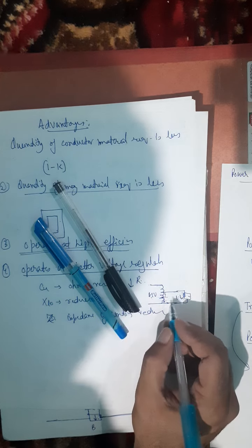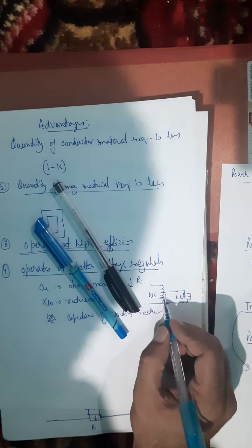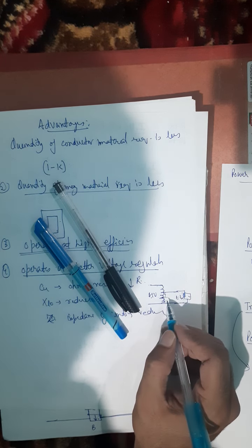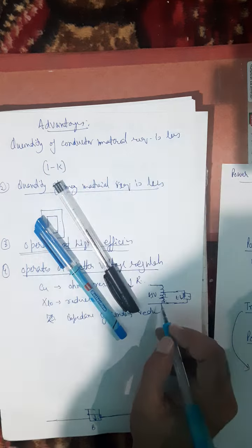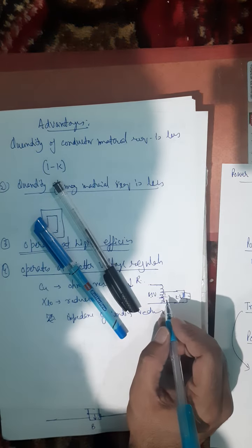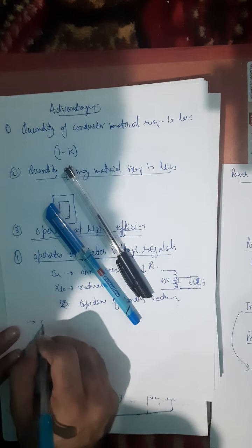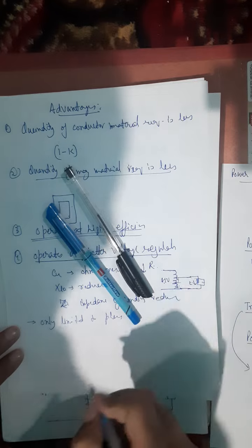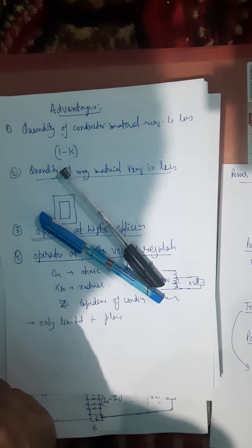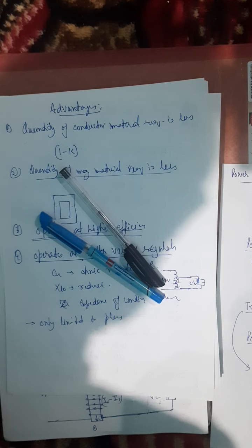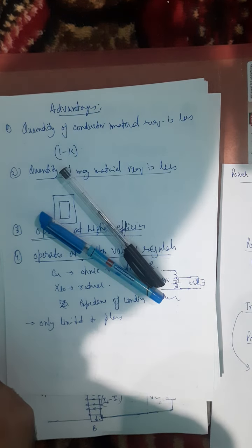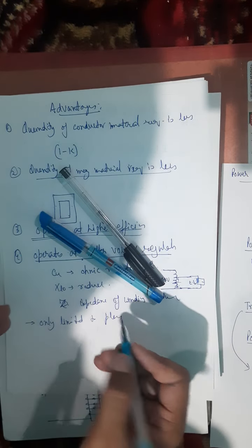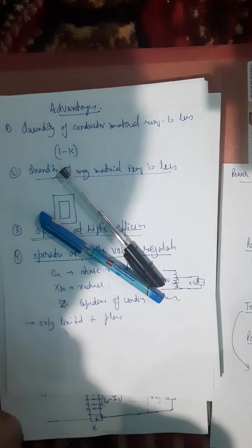Therefore it is advisable not to use this auto transformer for interconnecting the high voltage and low voltage systems. The use of this auto transformer is limited to places where a very slight variation of output voltage from the input voltage is required. In those applications, we use this auto transformer. Got it?